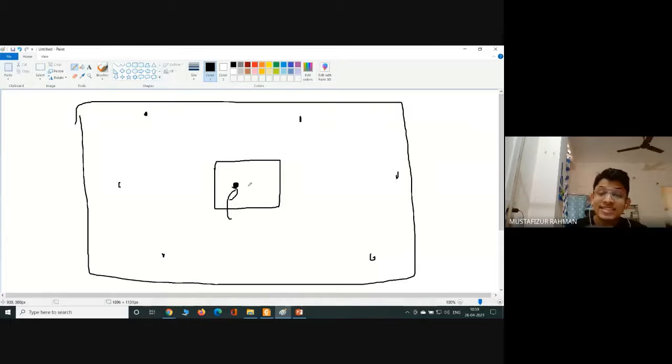So just as the name says, radiation, there will be a line from the central point to these points. We will have a ranging rod at this point. We will sight this ranging rod from this point with the help of an alidade, and we will measure this distance in the field.